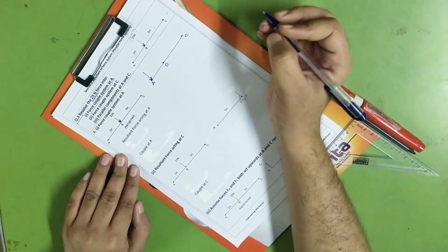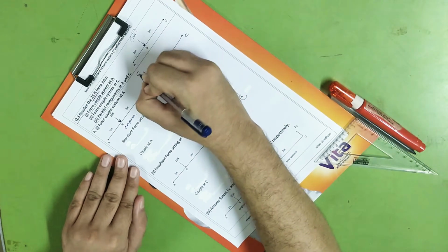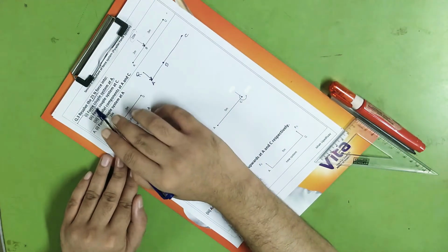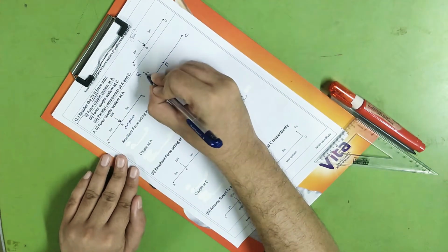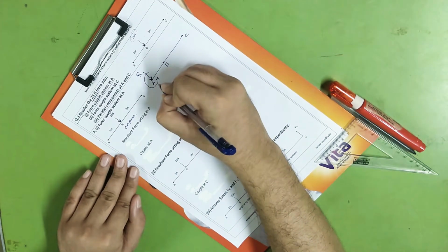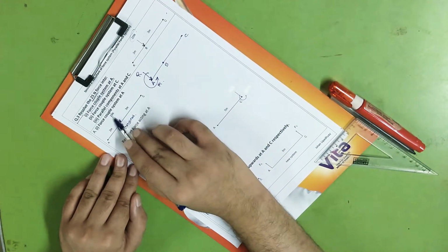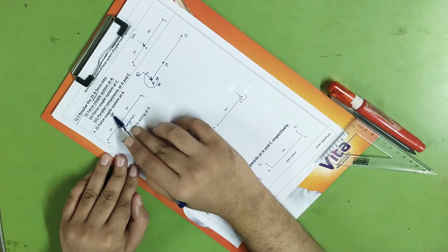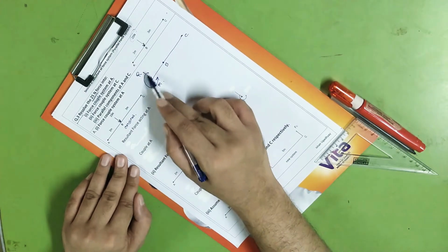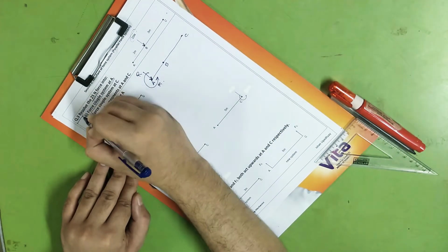So here I have drawn a downward force at point A. Downward is the direction I have assumed. Let me call it R. Okay, and a couple at A. So force and a couple at A. Here again I have to assume, let us say the moment is anti-clockwise, and I'll call it M. So what I have done is I have removed this 25 Newton force, and instead of it I am applying one force of magnitude R at point A and one moment at point A without changing the overall effect, because they are saying resolve.